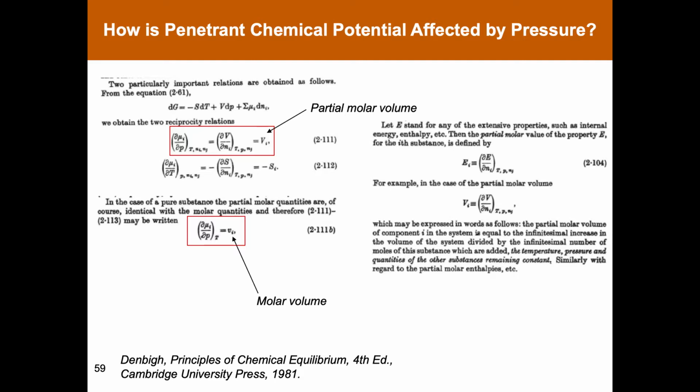And in a mixture, so if you've got say a membrane, say water dissolved in a membrane, the way that pressure affects the chemical potential of water in the membrane is called the partial molar volume. Okay? And it's going to turn out that the molar volume of pure water and the partial molar volume of water inside one of these desalination membranes are essentially equal to one another. But I just wanted to remind you of those definitions and the definition of the partial molar properties.